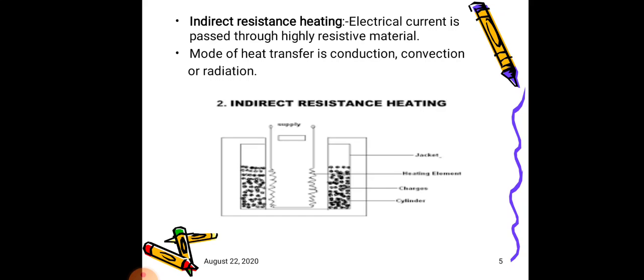element with passage of time breaks open and becomes unserviceable. Some of the factors responsible for this failure are first is formation of hot spot which shines brighter during operation, and second is oxidation, third is corrosion, fourth is mechanical failure.